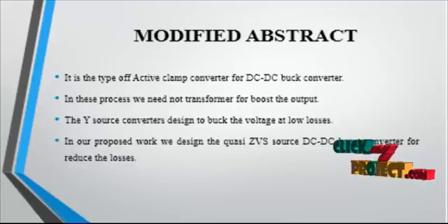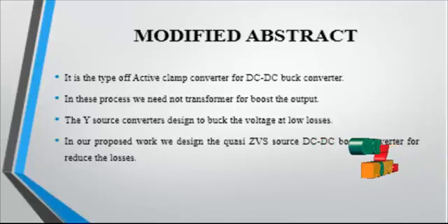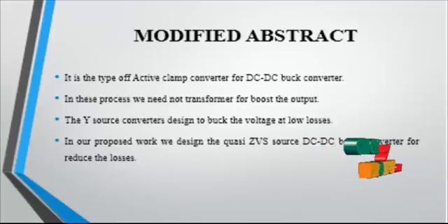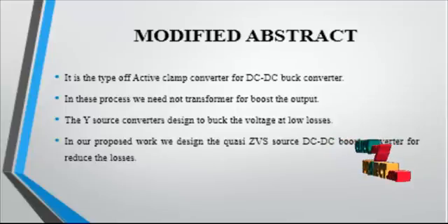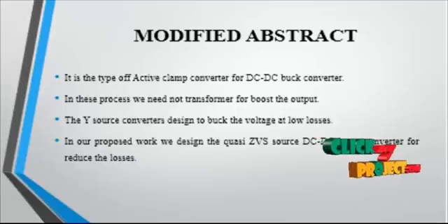A converter circuit proposed to reset the flux in the isolation transformer of a flyback converter developed into a new family of soft transition converters. Such converters are named active clamp converters. The analysis of active clamp converters has been presented with different topologies and different levels of approximation.